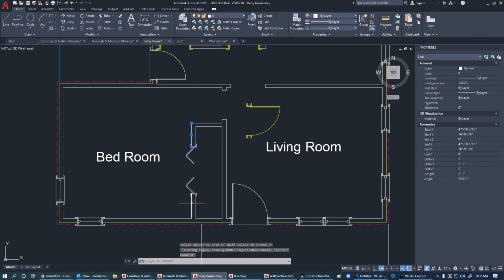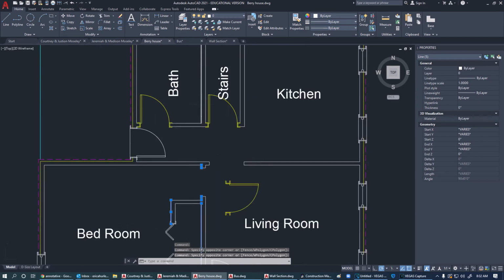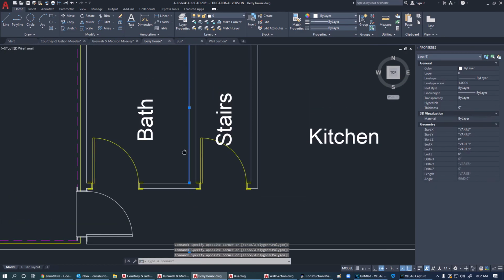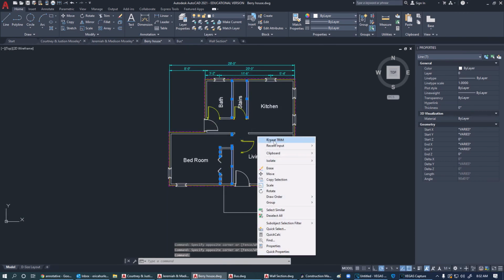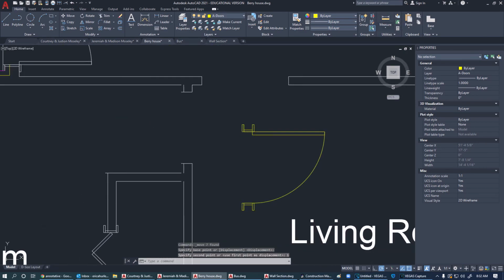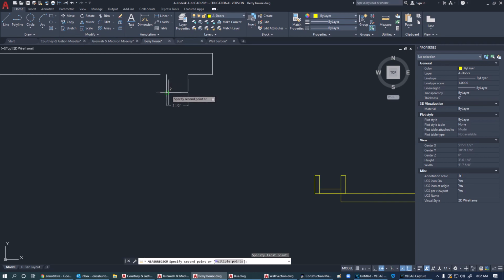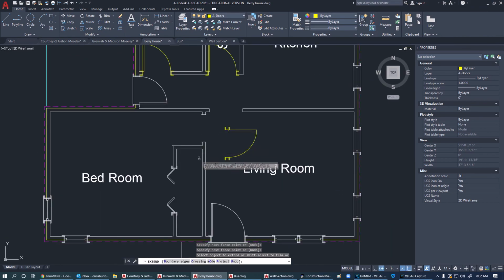Okay. So I need to finish moving my walls here a little bit. So I'm going to click on one side of all my walls. And I'm going to hit move 1 inch. So now all these walls are 3.5 inches. That is correct. And I'll explain why that is. Let me go over here to this wall section.